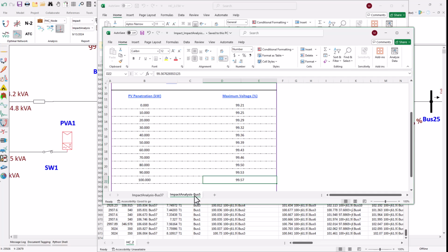When you have so many PVs operating in tandem, and when you are unsure of how many to energize and how many to not energize, it might be advisable to micro-analyze, to just focus on one bus and see if a certain bus has too many wild swings in voltage. So this study would be helpful to break down problems location wise.